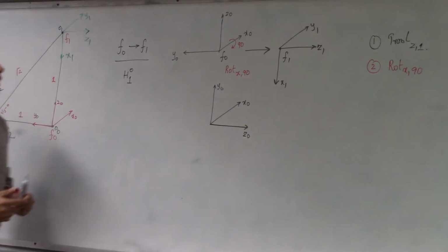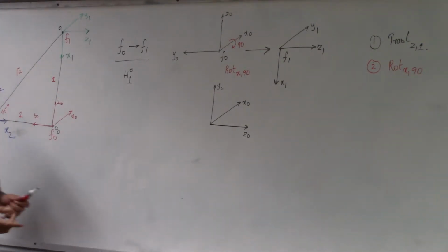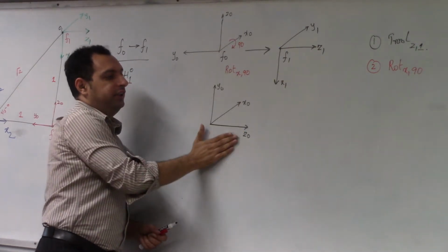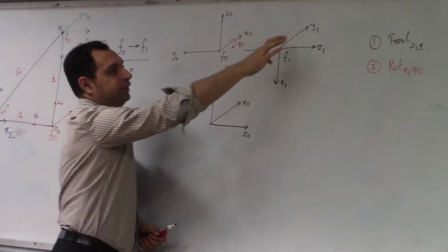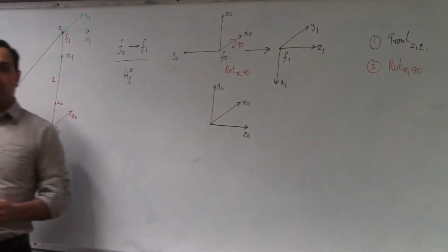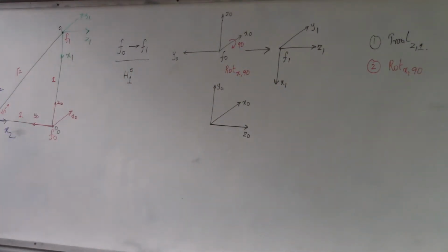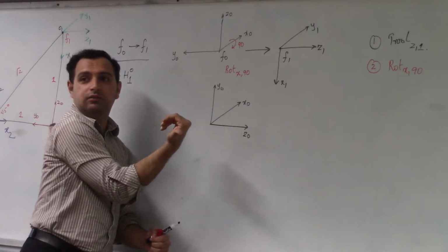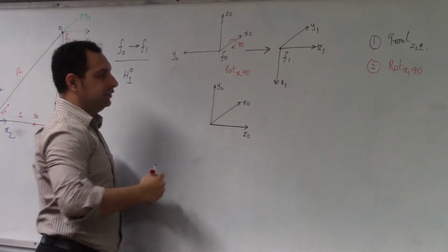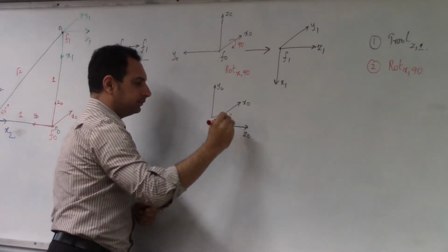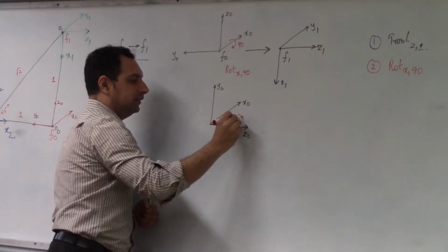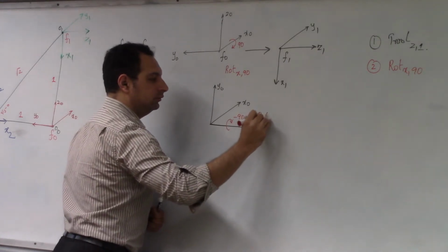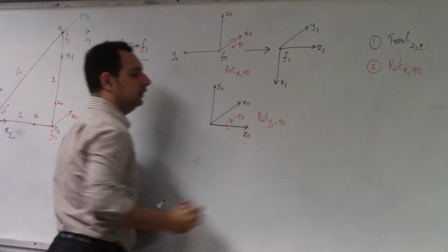Okay. Now, what is the next? So Z is aligned. I cannot touch Z. Z is aligned. Otherwise, I'll be undoing what I did here. Z is fixed now. Now, to align Y to this and X to this, how do I need to rotate? Along Z axis 90 degrees. Along Z by 90 would be like this. That would bring Y outside the board. Minus 90 degrees. In the opposite direction, in the negative direction. So here you'll rotate negative 90.